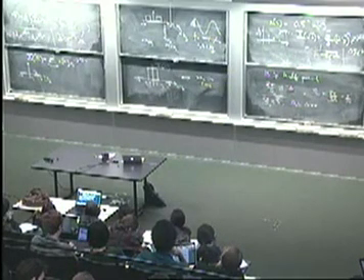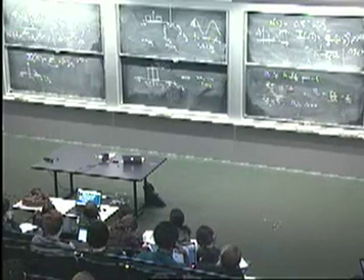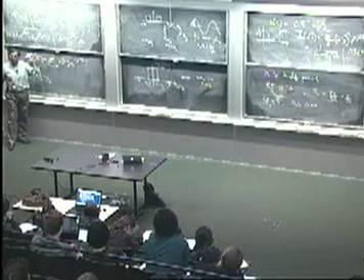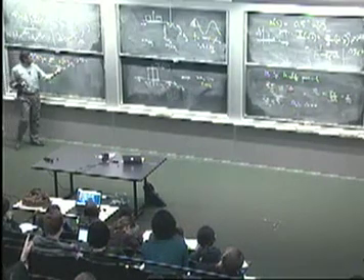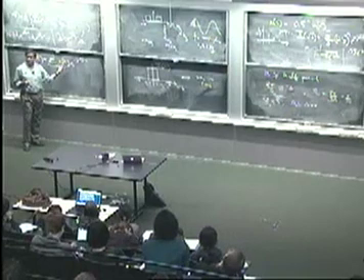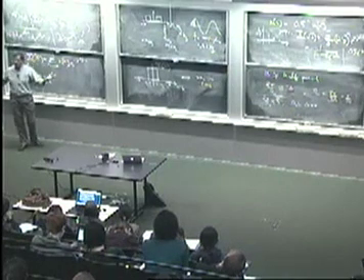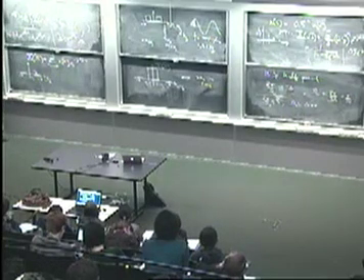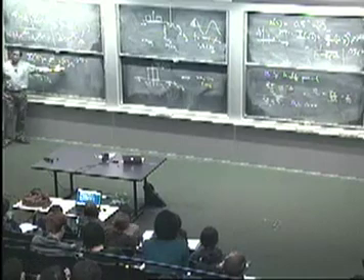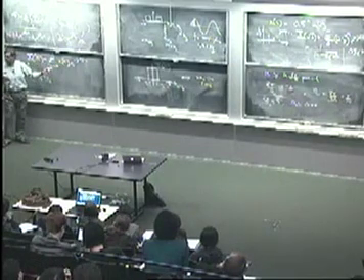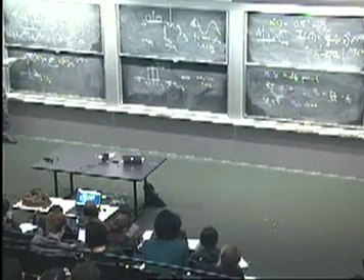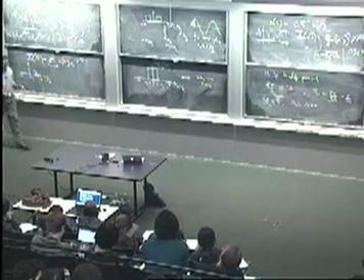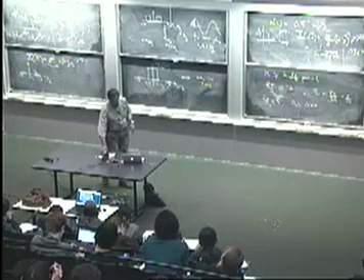Any thoughts here? It's unlikely that my summation is going to go from minus infinity to infinity, because I'd be waiting a long time to collect that signal, right? So in practice, what we're dealing with are signals of finite duration, typically assumed to be 0 outside of that interval, though you might have reasons in some contexts for assuming otherwise. We're always going to take finite length signals. So the summation will be over a finite interval. And we're going to want to compute the DTFT on a finite grid of points. And that makes for some simplifications.